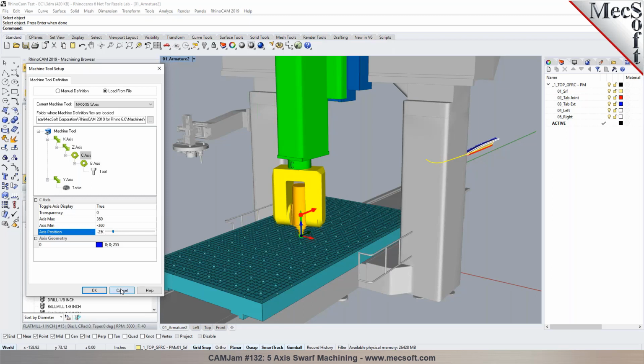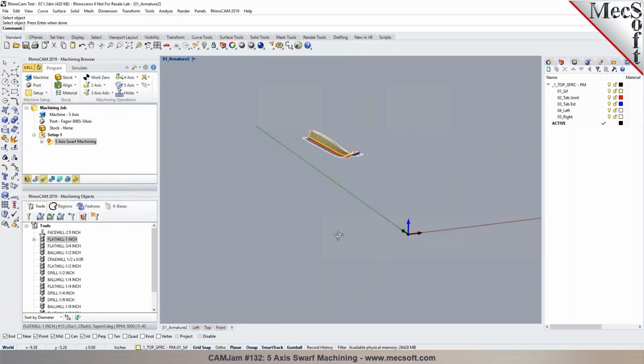Great, thank you. Okay, all right, so I forgot to mention the orientation and location of the origin. I thought you already had it placed where you wanted. So that would be your XYZ origin for machining. Is that correct? Yeah. Okay, so I have not changed it. So basically all your toolpaths will be computed and output based off this as your 000 location.